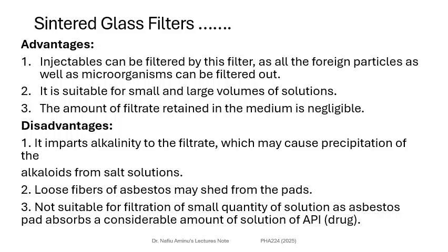What are the advantages of these sintered glass filters? Injectables, which we call parenteral preparations, can be processed by this filter, as all the foreign particles as well as microorganisms can be filtered out.